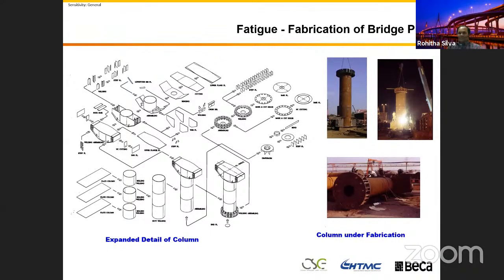Some designers, because the codes already give you the minimum thicknesses of the weld, try to save 1 millimeter of the weld, but at the end of the day, they are creating stress. That 1% saving sometimes affects performance, like a 10-15% risk. So you need to see all those things.